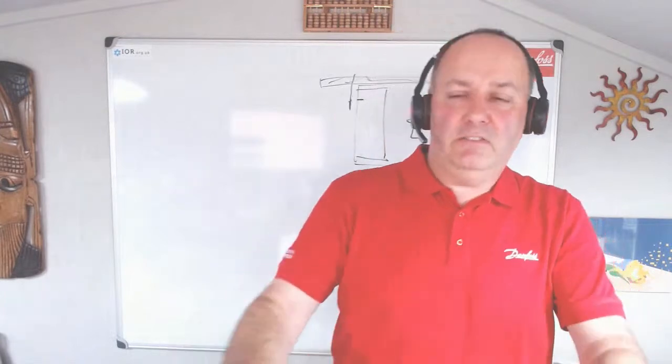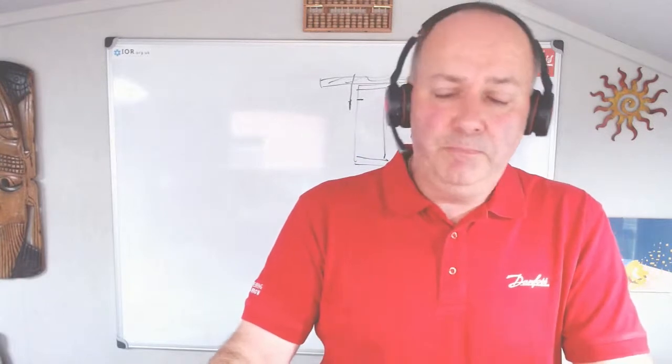Okay, what is the right time to start a defrost cycle? It sounds like a daft question, but it's actually not a daft question. A famous person once said that there's no such thing as a stupid question, only stupid answers. So for me, any question is always good. If it's a general cold room or freezer room, defrosts equally spaced throughout a 24-hour period, 3-4 defrosts a day, 20 minutes, 30 minutes duration each defrost, generally works fine.